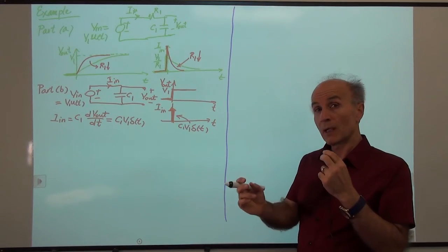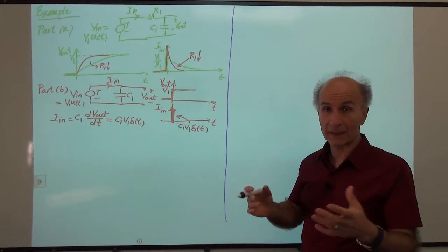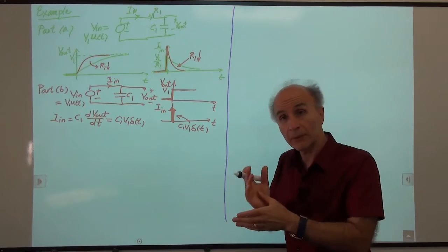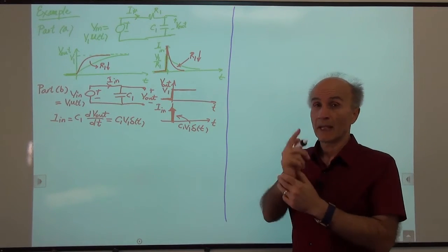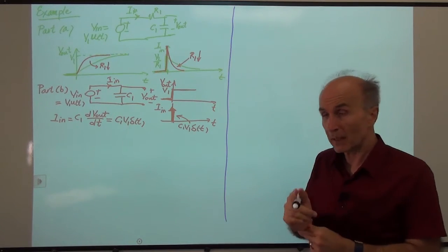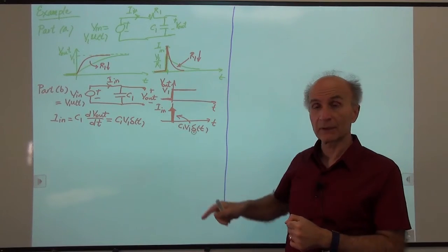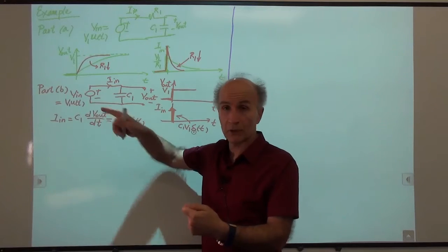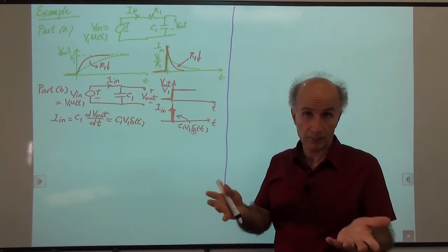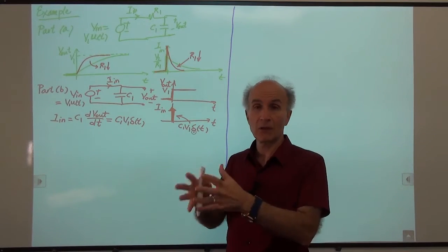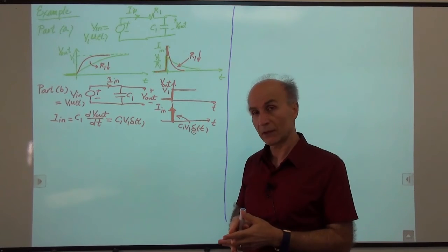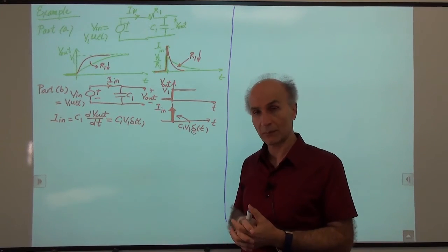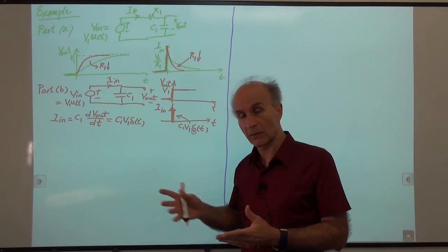Okay, so one thing that we see here is that the voltage on the capacitor jumped in 0 time. That was possible because we could provide an infinite current. And that was possible because we have an ideal voltage source available to us. An ideal voltage source, by definition, delivers any current we want, including an infinite current. Of course, in practice, that's not possible, but we can come close to this scenario.